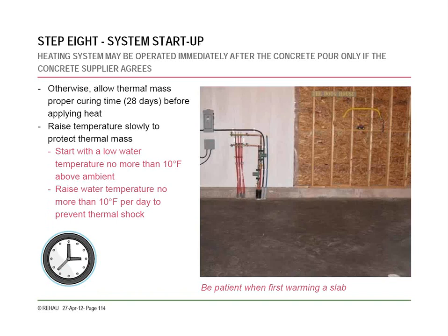For system startup, you want to make sure that your concrete is cured. Check with the concrete guy on that. You want to start with lower temperature water. Obviously, you're just going to pipe in the city water and then bring it up to temperature. Here they show raise the water temperature by no more than 10 degrees per day to prevent thermal shock. So check with the concrete guy again on this, and proceed accordingly just to make sure that you're not messing with his slab.